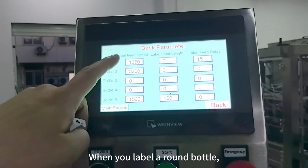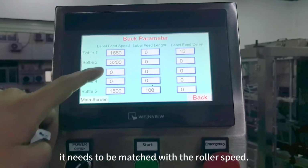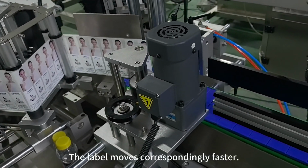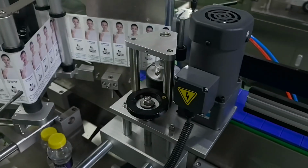When you label a round bottle, the label feeding speed needs to be matched with the roller speed. The faster it rotates, the faster the label moves correspondingly. This is just for sticking round bottles.